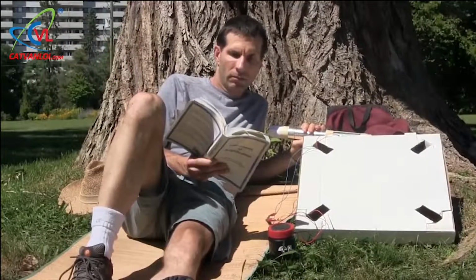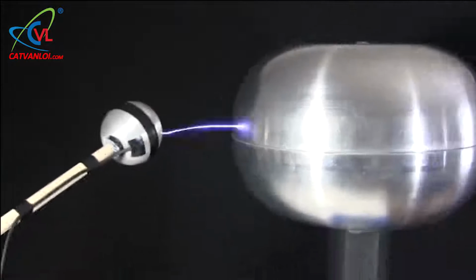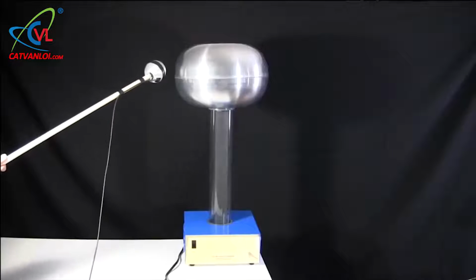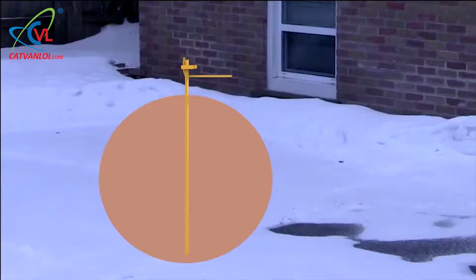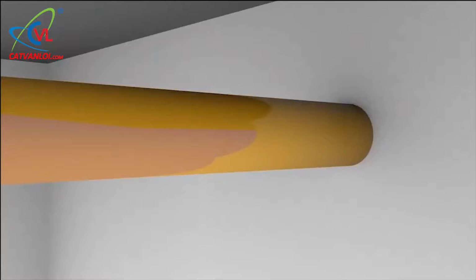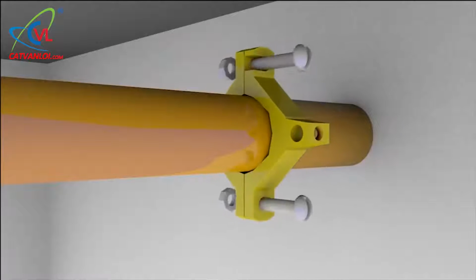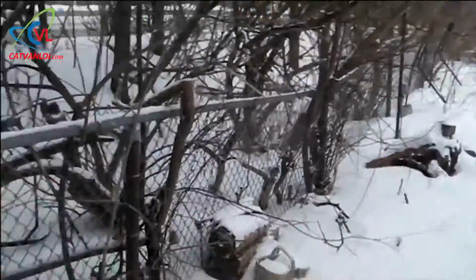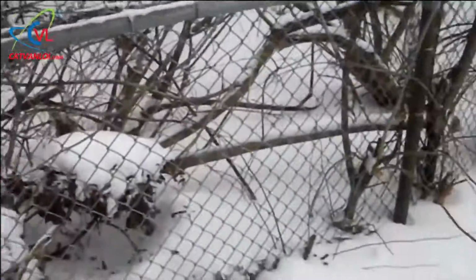Here, I'm the ground. Often when playing with high voltage, you'll have a ball that's connected to a wire going to ground, and make a spark by bringing that near a charged object, like this Van de Graaff generator. A fairly safe way to ground that, if you don't have a ground rod that you can connect to directly, is to find a metal pipe that you're certain goes into the ground, like this copper cold water intake pipe from the city, or this metal fence would do, since it makes plenty of contact with the ground.